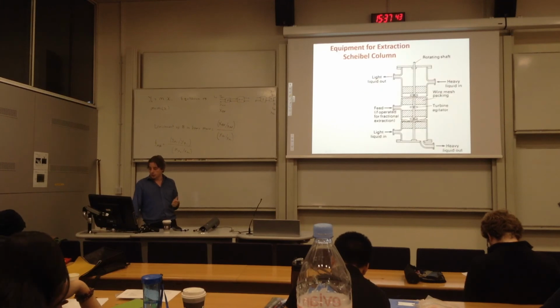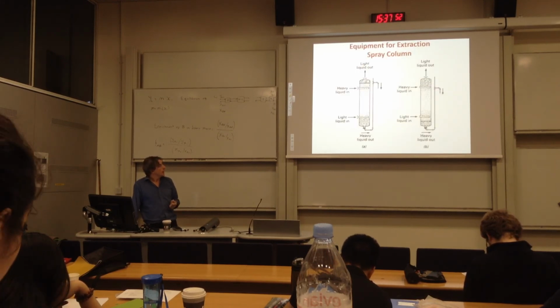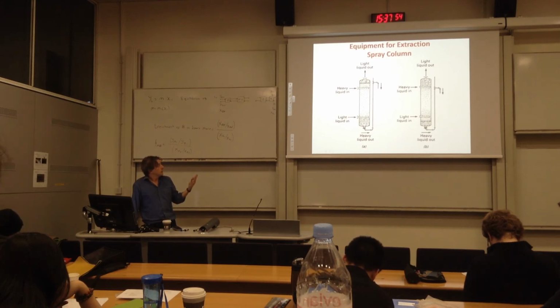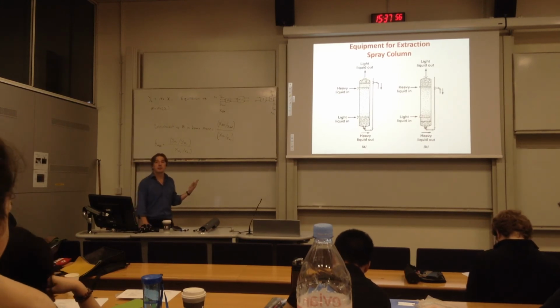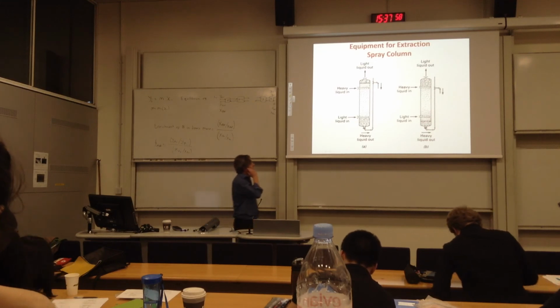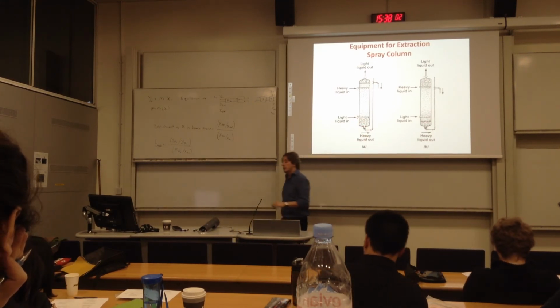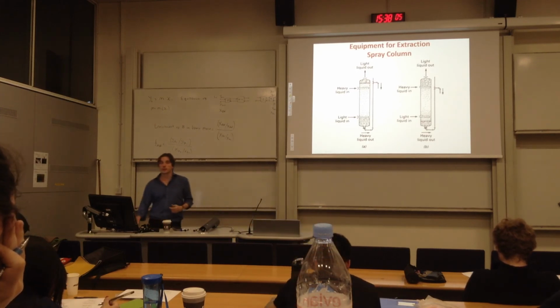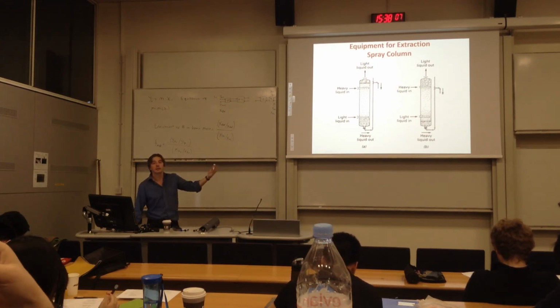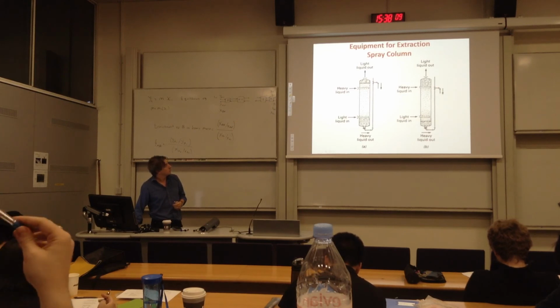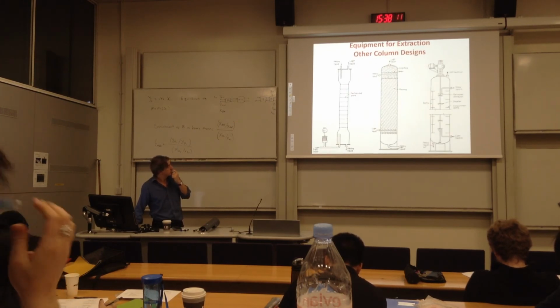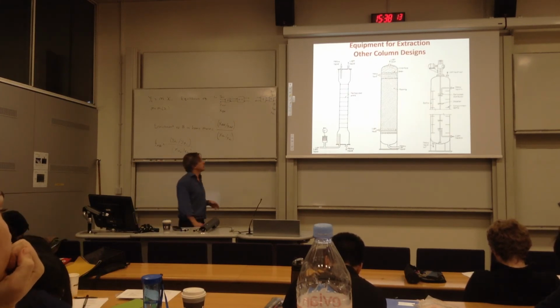Well, there are various different designs, all based on the same principle. There can be some mechanical agitation instead of baffles. The particle size can be made smaller, by having a fine spray there, improving the contact area, but again it's another design with the same basics.